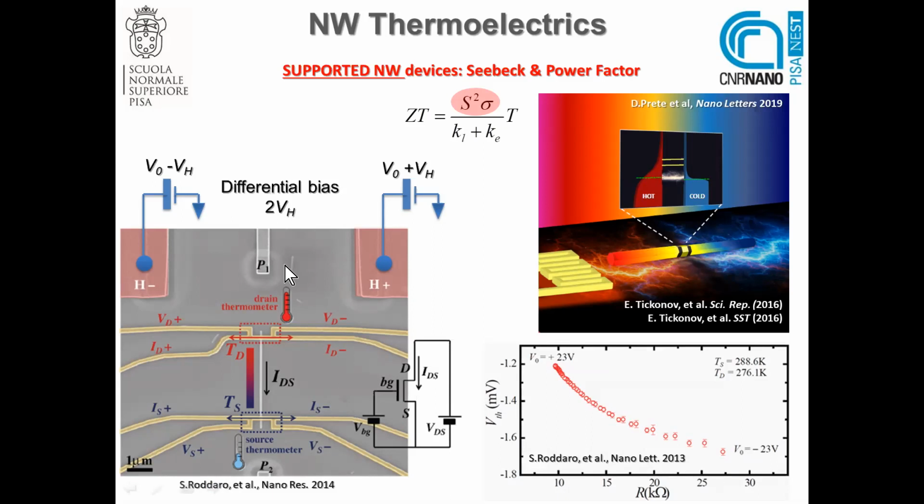left of the screen. So basically this is your nanowire. You have to fabricate electrodes at both ends that allow you simultaneously to measure the current across the nanowire, so to measure the IV characteristic of the nanowire, and at a time to measure the temperature at both ends, the hot end and the cold end. And in order to have a cold end and a hot end, you need to establish a temperature gradient parallel to the nanowire, sorry. Yeah, and to do this, well, you can go for a couple of options at least.